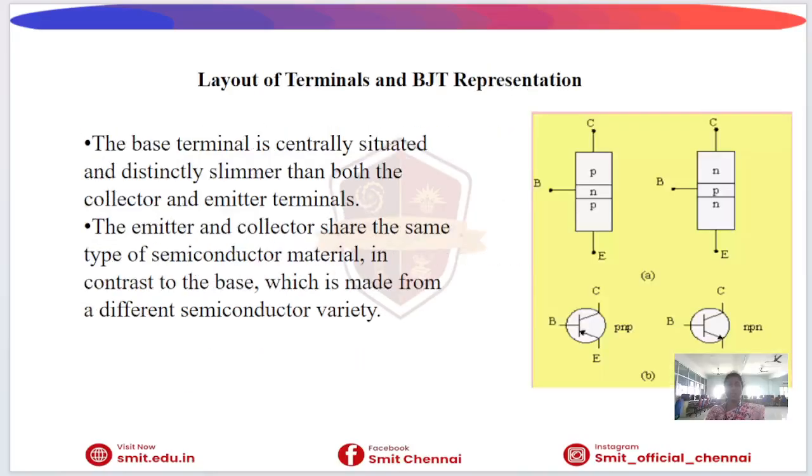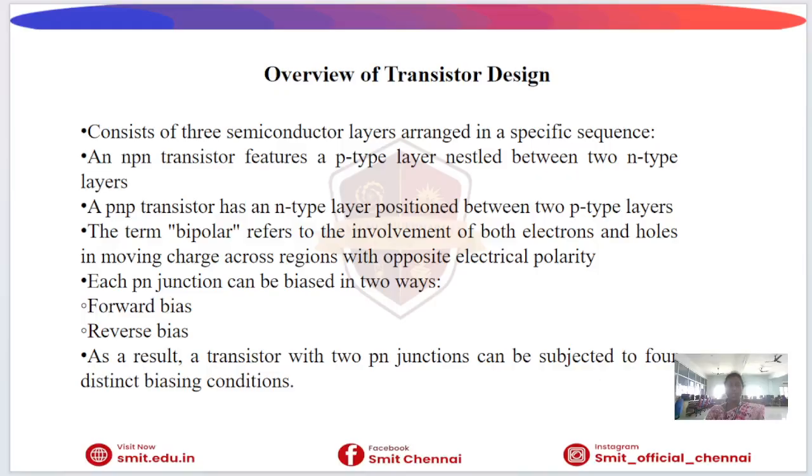And why is it called bipolar? The term bipolar is used because two types of charge carriers, electrons and holes, participate in the conduction. In a MOSFET, we mainly depend on one type of carrier, but the BJT is bipolar, using both. Hence the name bipolar junction transistor.